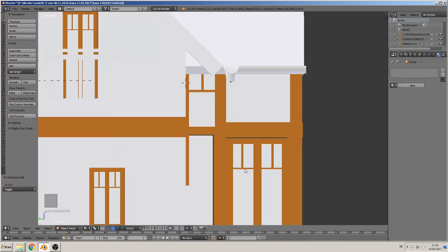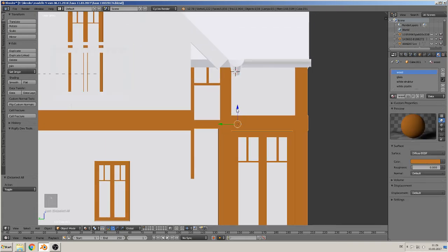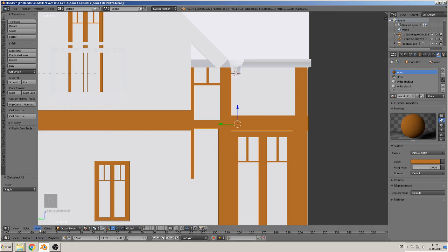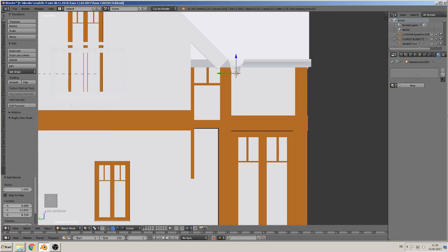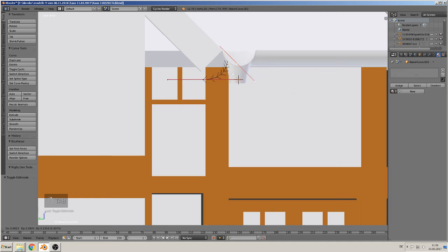That we make with a Bezier curve. That means we click here. Oh, we see here some arrows. We must tweak that later. Okay. But add curve, Bezier curve, rotate X 90 degrees, rotate Z 90 degrees. And now we see here our curve. Scale them a little. Go in edit mode. Position the first one at the start. Then get the second one.